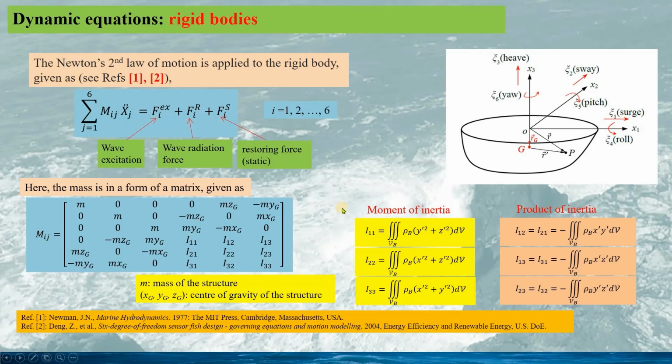It should be noted here, all the moments of inertia are with regard to the principal axes, that is, with regard to the center of gravity of the floating structure, regardless of whether the reference point, the origin of the coordinates in the plot, is the same as the center of gravity or not.